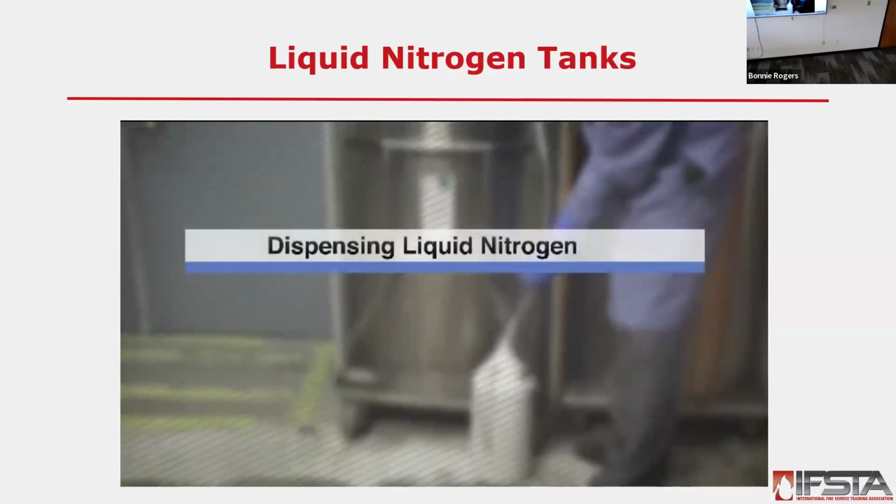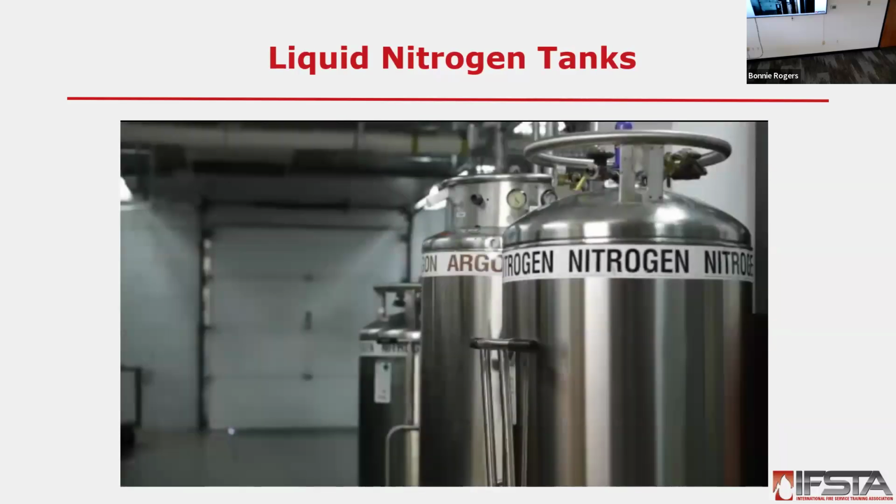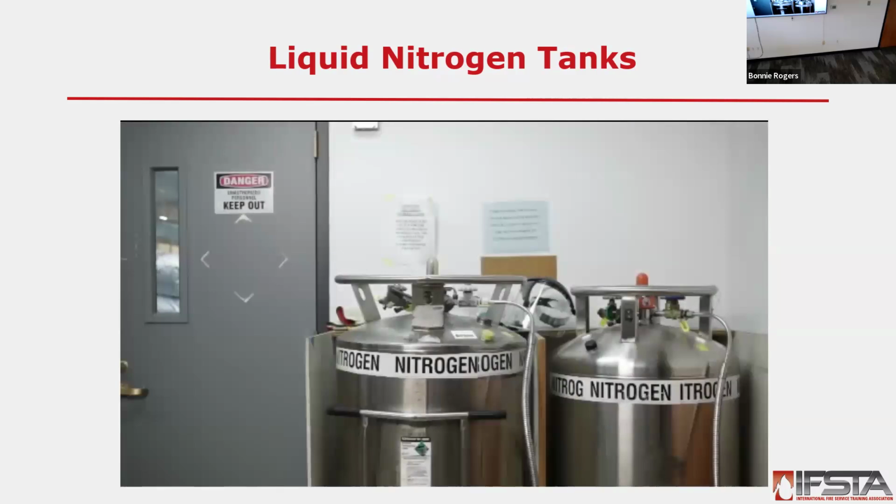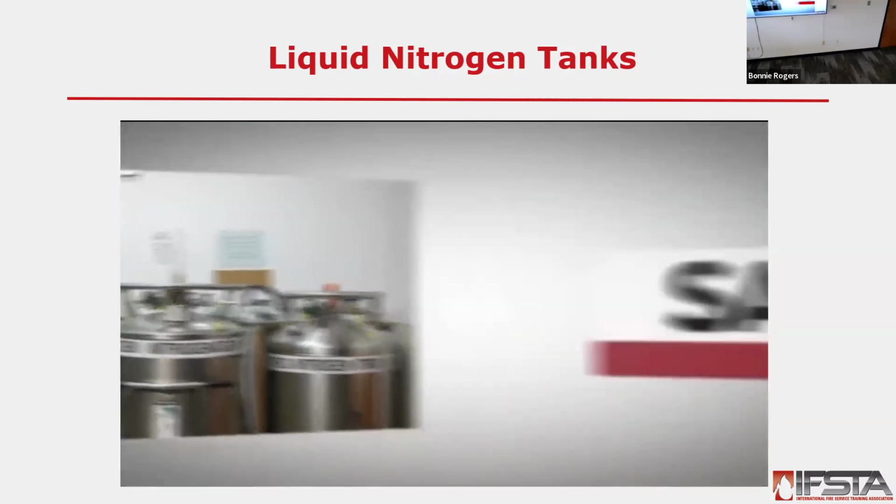Dispensing liquid nitrogen. Liquid nitrogen tanks should always be stored and operated in areas with plenty of ventilation. Liquid nitrogen tanks must always be stored and operated in the upright position.